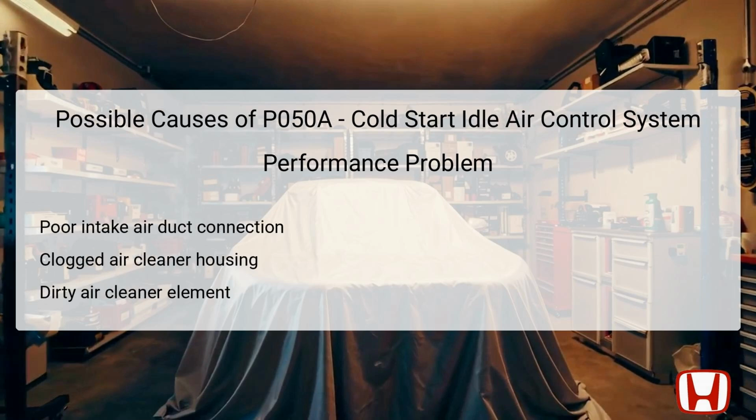Several factors can contribute to the DTC P050A. A poor connection or blockage at the intake air duct can obstruct airflow, disrupting the performance of the idle air control system. Compromised connections may lead to unintended air leaks, affecting how the engine functions under cold start conditions.